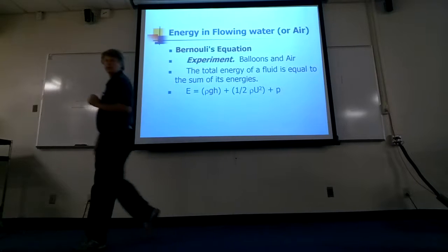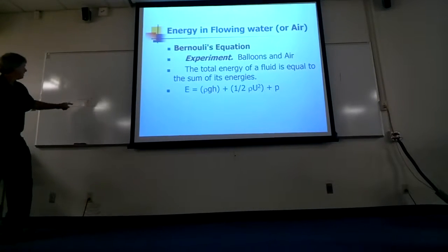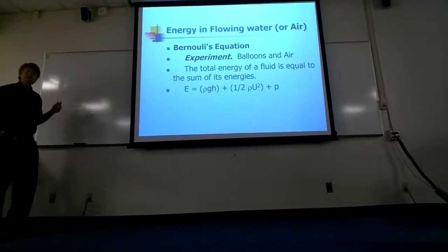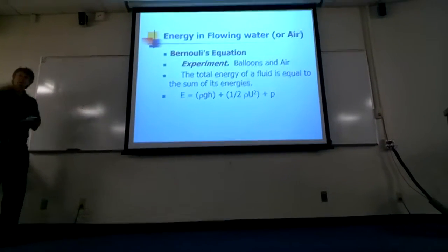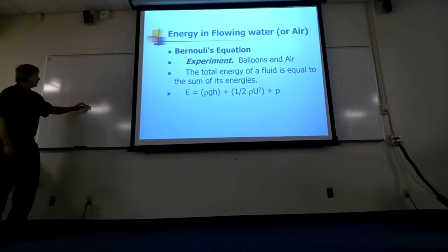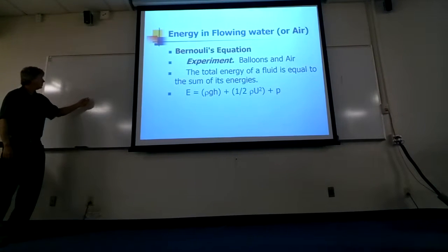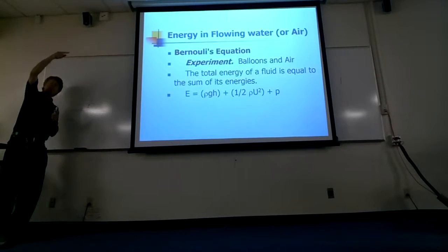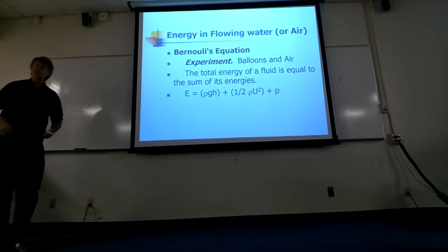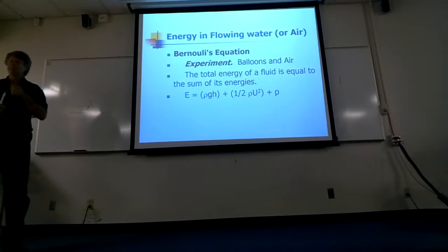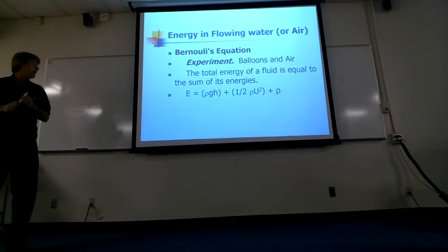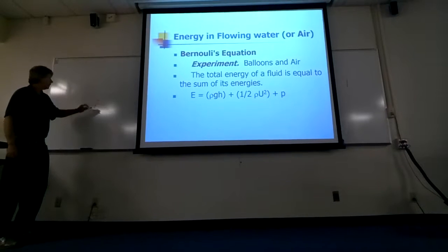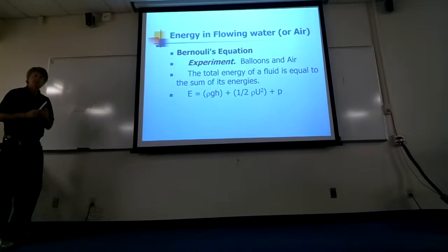And so there is a lift that's provided by the Bernoulli equation that is proportional to the square of the velocity. So in other words, the faster the river flows, or the wave, or any current, any fluid, wind blowing over a sand dune, the faster it flows, the more it tugs at sediment lying on the bottom and tries to pop it up into the fluid so that it'll move. Make sense to everybody? This is the main reason why wind and water carry sediments.